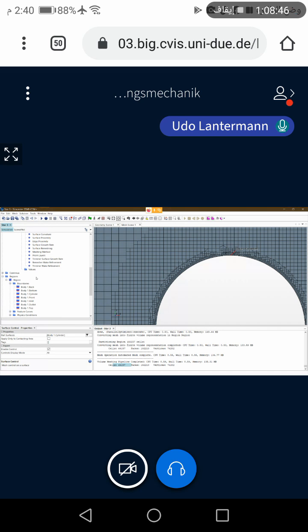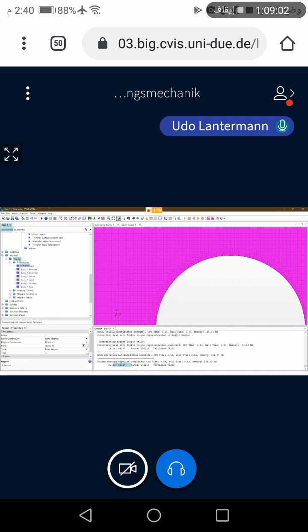We will create the mesh again. Let's first set our boundary conditions. So, to set boundary conditions, we have to go to the section regions. And region is our created region, the computational domain. And under the section boundaries, we will find the different boundary patches.